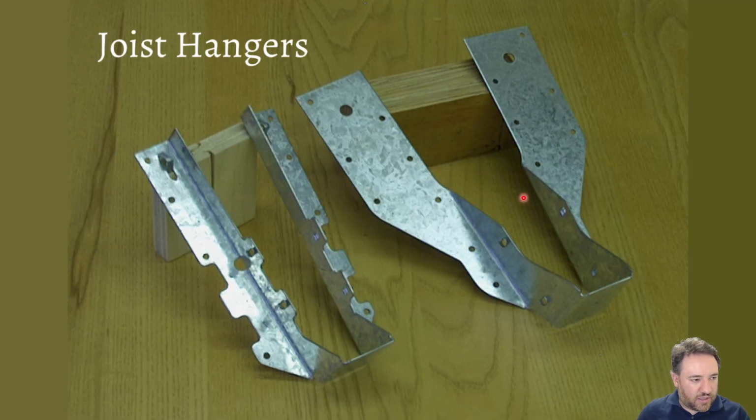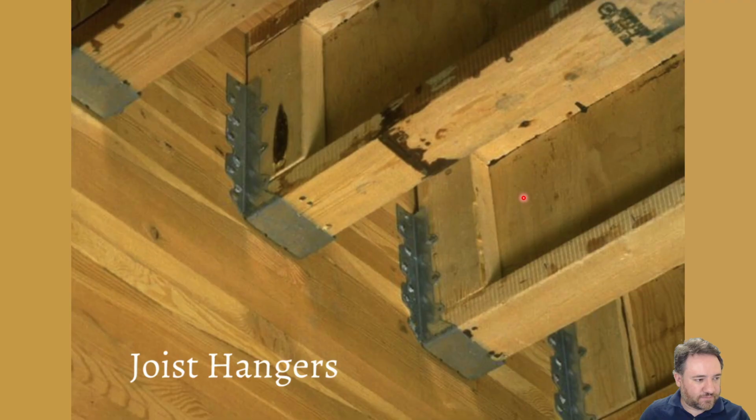Okay, when we connect joists to beams and stuff like that, often we're going to use joist hangers, which we have seen before. These are just members that connect between a joist, and this one in the back is a larger timber member, and those are almost always also connected with nails, usually using a powered nail gun to make installation a little bit easier.